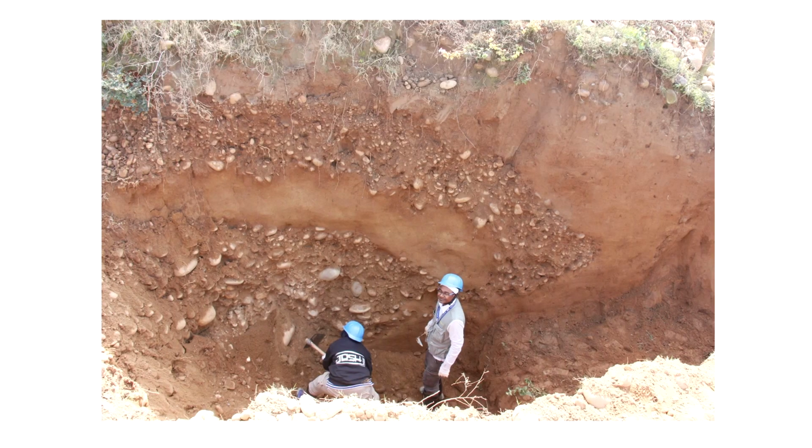In this trench, if you quickly look, you have a gravel unit which is bending here, and then it is following this line. There is another contact. If you mark these sharp contacts, that can help you in understanding what is happening. This is another one, and this portion has been overlaid. This is your soil unit in between, and this is another contact, what we call the bounding surfaces. So this is a quick interpretation you can do: you see a definite and very prominent deformation in this area.